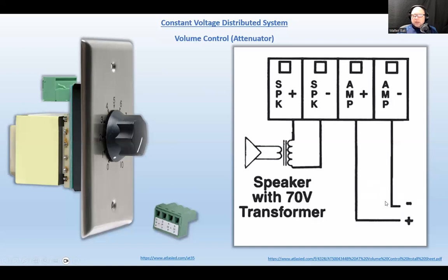Over here, you would have the primary side of this transformer, these input terminals, and here's the connector, and here is the connector right here. You would connect this to the main audio, just tap into the plus and minus conductors for the signal. And over here at the other terminals, it's an output.